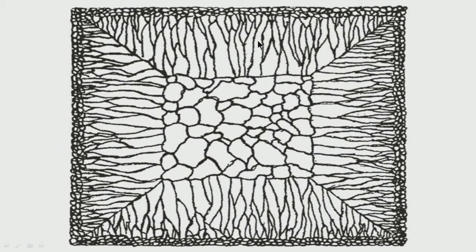So, what is important to remember is that this ratio of columnar zone to equiax zone depends on superheat. That means, the actual temperature of the liquid steel which is getting solidified, during casting, how high is it, what is the difference of this temperature with the liquidus temperature. So, that is called superheat. Lower the superheat, more will be the equiaxed zone.